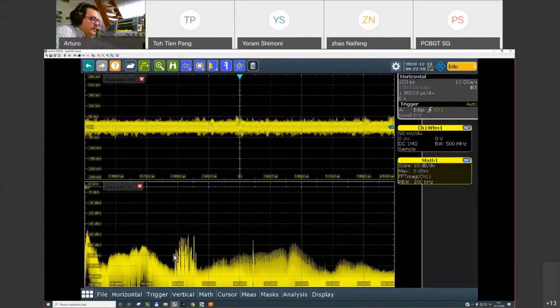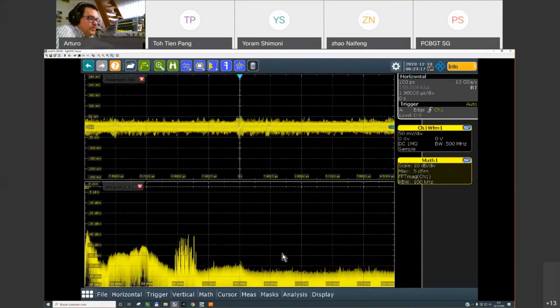You will probably obtain the frequencies from 88 to 108 megahertz that are related with FM broadcasting. You have some kind of broadband low frequency noises created by switching mode power supplies, I don't know, your phone chargers or any kind of soldering station or switching device close to your circuit, lightning, using LEDs, I don't know, many things. Let me switch off my soldering station. You can see that the energy disappeared. So this is the environment I have in my laboratory.